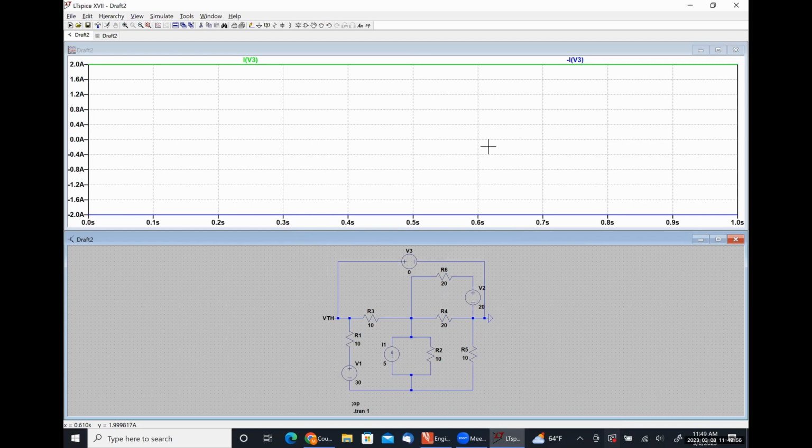And we're going to use LTspice later on when we're looking at transient analysis problems, where we are simply going to simulate our circuit. And then we are going to type in a mathematical expression and compare the two things. And if they perfectly match, then obviously we did it right, because our analytical solution matched the simulation. If we made an error, it's not going to tell us where our error is, but we're going to see very obviously that there is an error because our work doesn't match the simulation.